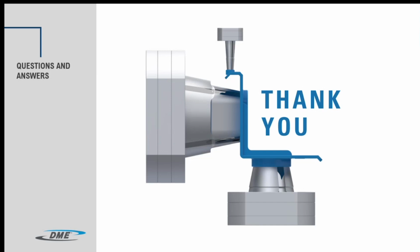Okay, and for medical parts, can you run greaseless? We don't recommend operating the DuraCore or the S-Core without any grease, although it is a very light application of grease, very light. DME offers several high-performance grease solutions that won't break down over time, which allows for longer preventive maintenance cycles. But we do recommend that the segments are greased.